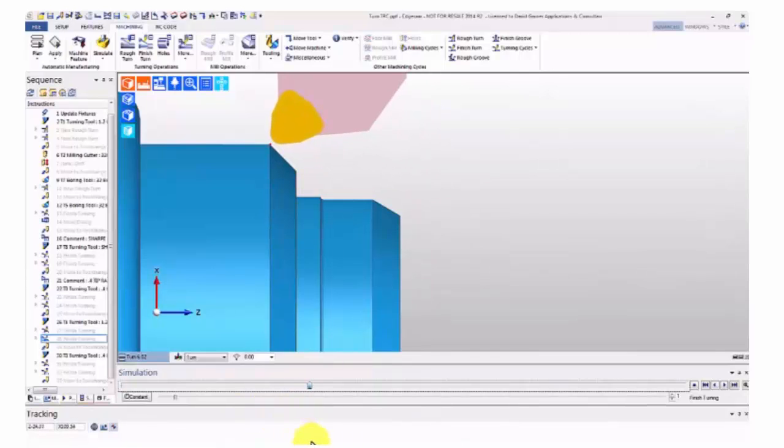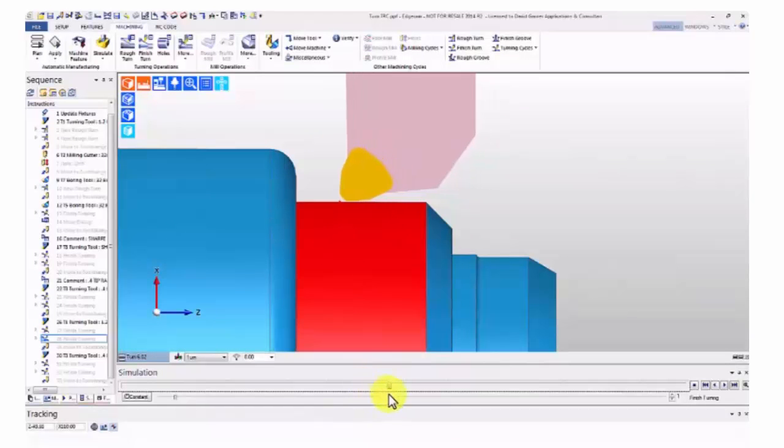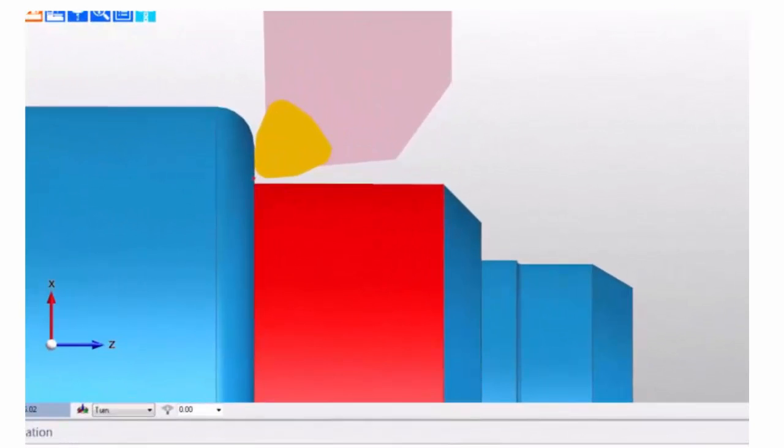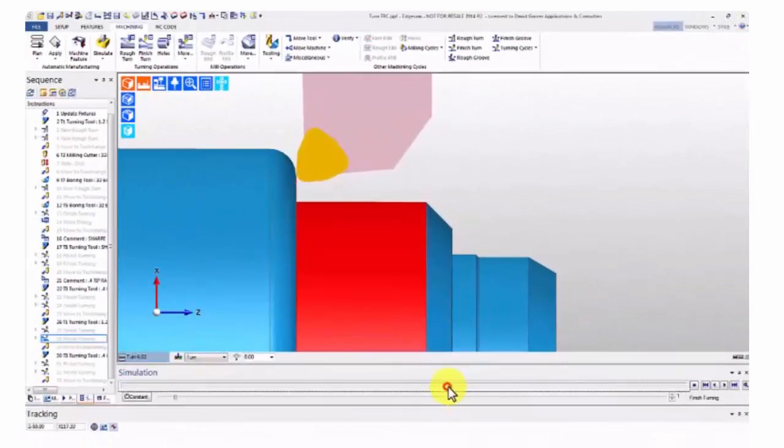And then if we watch it go around this rad, it's actually going around. But can you see how the path's actually distorting as it goes around the rad? It's not actually producing a path that's the same like a bigger rad. It's actually distorting as it's going round. And that's what you're doing when you're not using tool nose radius compensation. That's what you're actually producing.